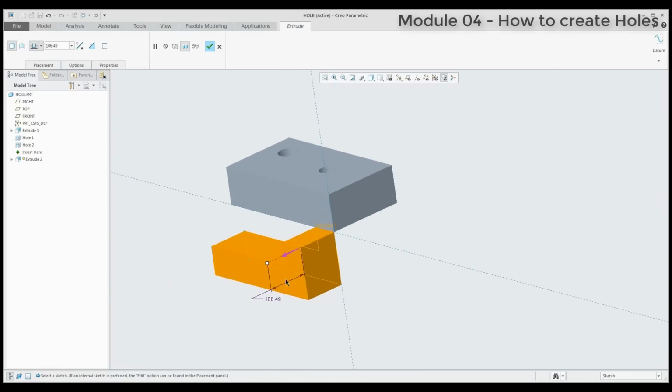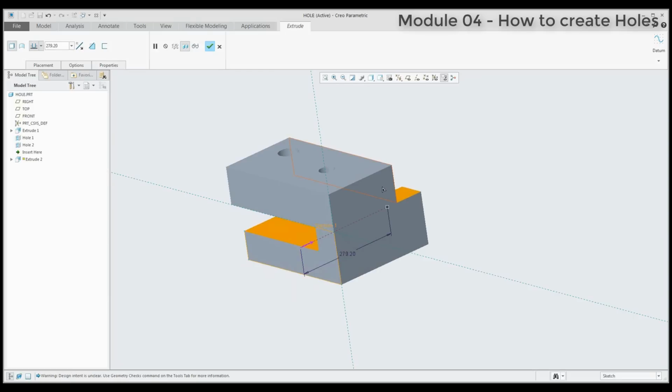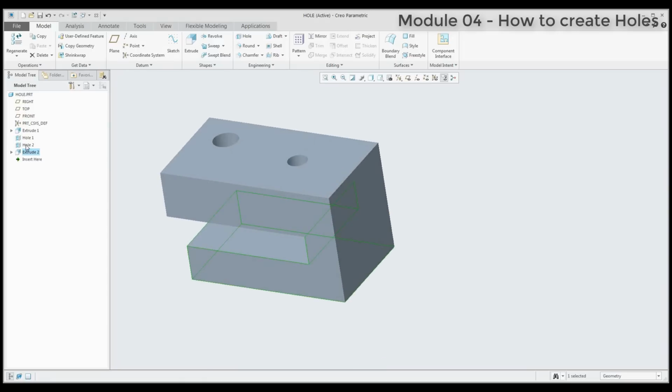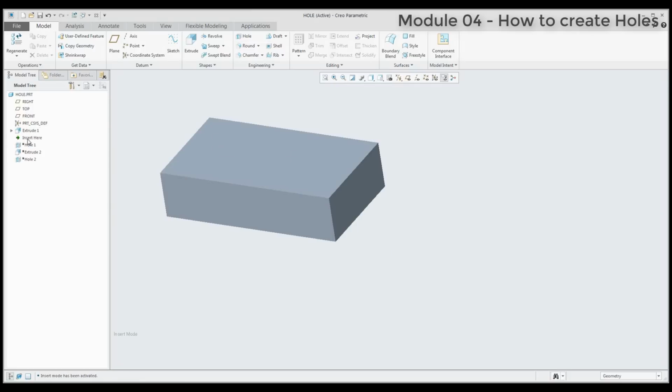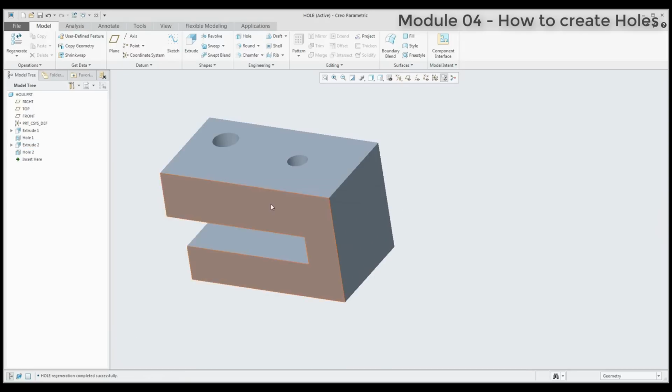Okay, so I like the extrude feature on the backside surface. You can really easily select the Shift button and snap to that surface, and the system will create the function to select it. So the system automatically jumps from the specification of the depth to the selected reference. And right now I will move my hole to, and the system reads the model tree like you see here from top to bottom. Extrude, hole 1, extrude 2 and hole 2.